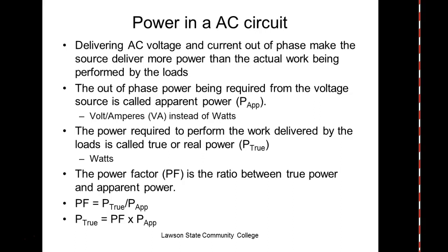So if I could get 75,000 volts DC, it would be more efficient to send that, because now we're only worried about the resistance of the wire. We're not worried about XL and XC anymore. We're not worried about impedance. And there's a tendency to move back to DC on really long distance lines, where they electronically make DC and send it on.